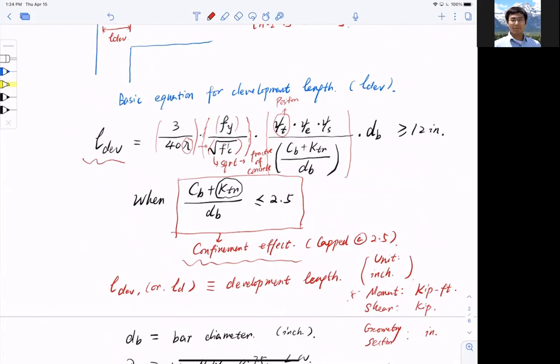And again, the reason is because the more concrete under the bar, the more aggregate segregation. Again, I want to give a picture of what aggregate segregation is, right? If you're ever on site when concrete is being poured in, when they start pouring, you see all these aggregates pouring together with the cement, together into the formworks, right? So as you have more depth underneath the bar.